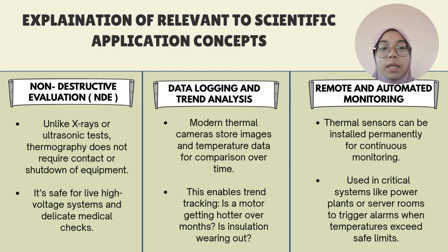Last but not least, the last application in the thermography concept is remote and automated monitoring. Thermal sensors can be installed permanently for continuous monitoring, used in critical systems like power plants or server rooms to trigger alarms when temperature exceeds safe limits.